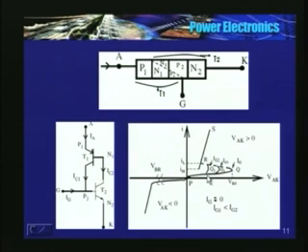In the forward bias mode, if the current is very small, equal to the leakage current, I told you the device is in forward blocking mode, again it is stable, that corresponds to P to Q, or P to Q1 or P to Q2. Assume that you are not supplying any gate current.